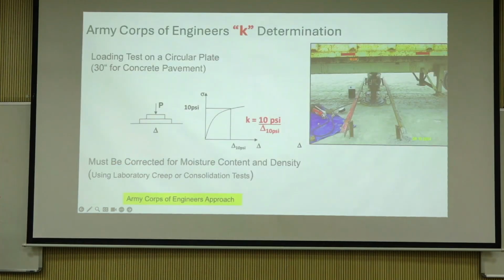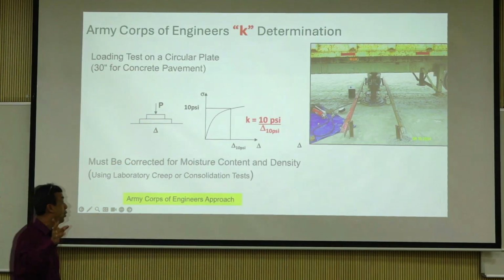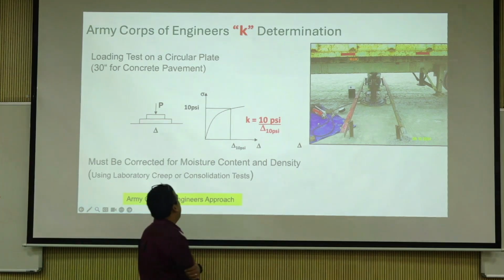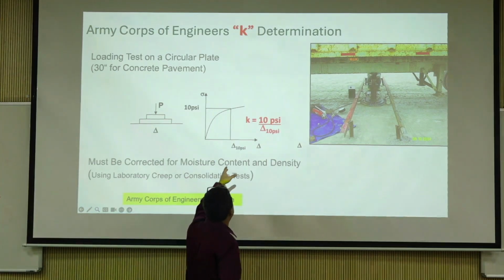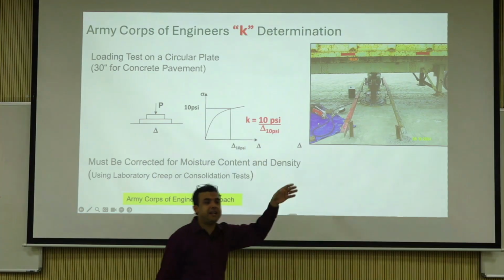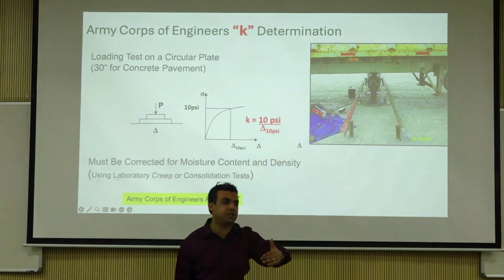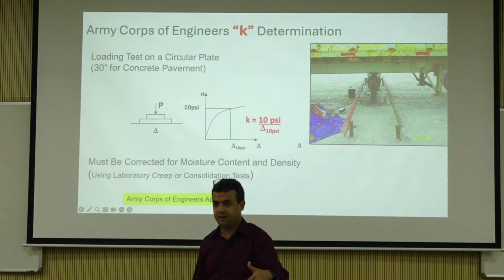So how do you measure? There are different types of measurements. I don't know about the Indian standard, but the Army Corps of Engineers, they actually measure at 10 psi divided by the corresponding deflection at 10 psi.